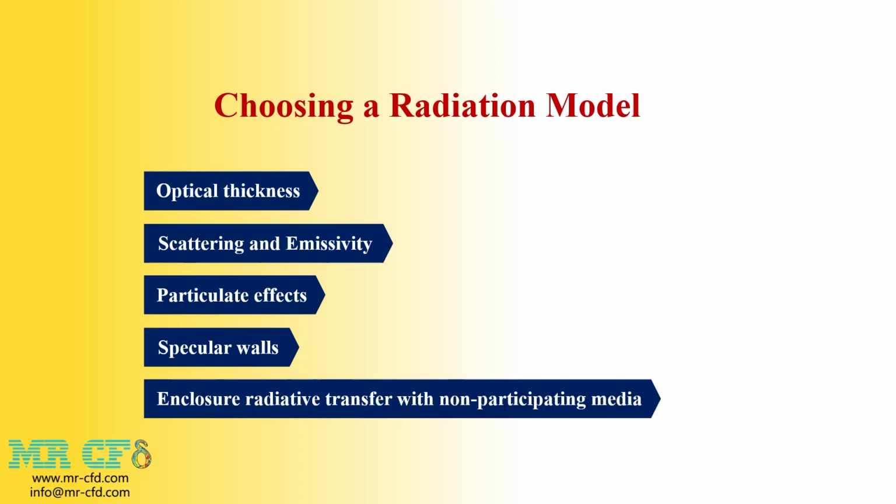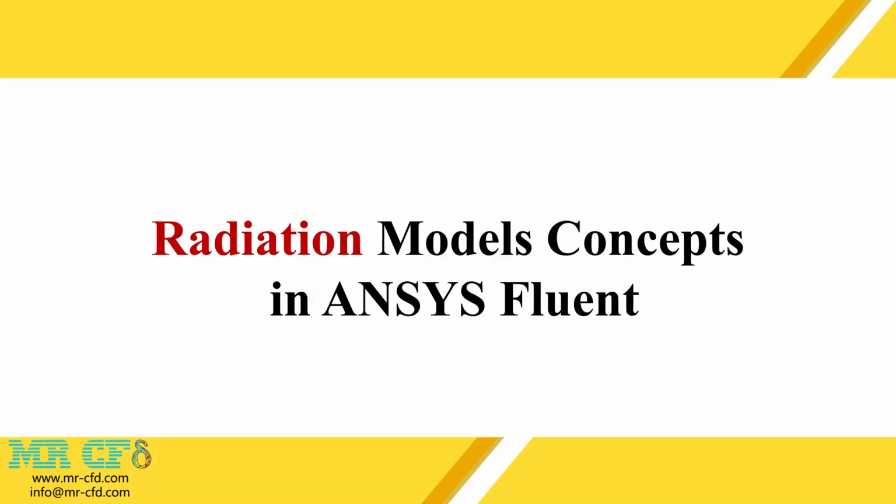The fifth criterion is the effect of the presence or absence of the participating environment in the radiation space. Regarding the participating environment, we have already provided the necessary explanations. Now, if radiant heat transfer occurs inside a chamber with a non-participating environment, the S2S radiation method is considered the best proposed option. Of course, we should point out that the S2S method may also be effective in a model that has a participating environment, but it is not always efficient.